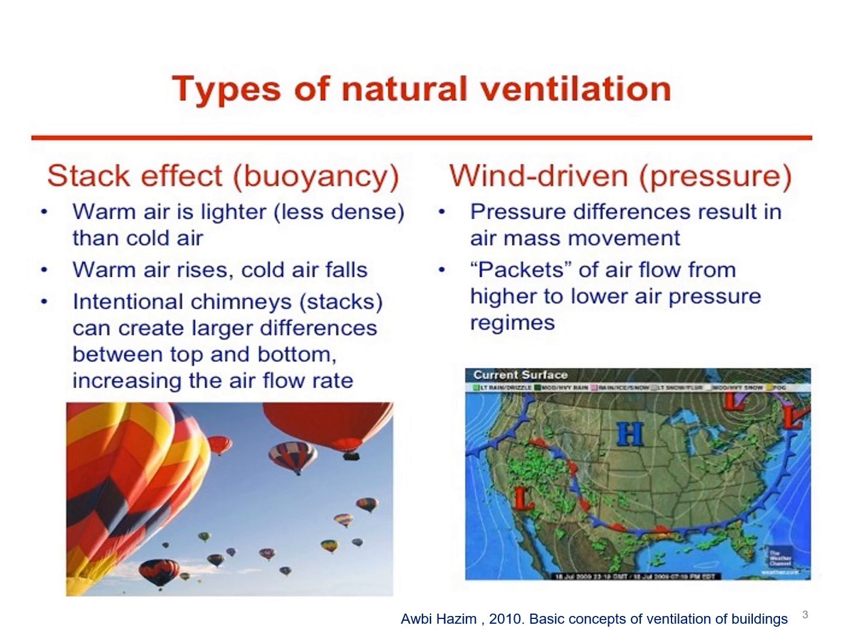In stack effect, the principle is that warm air is lighter, less dense than colder air. Warm air hence rises, cold air falls. Internal chimney stacks can create larger differences between top and bottom, increasing the airflow rate. The wind-driven or pressure type of natural ventilation is based on the principle of pressure differences, which results in air mass movement, pockets of airflow from higher to lower air pressure areas.